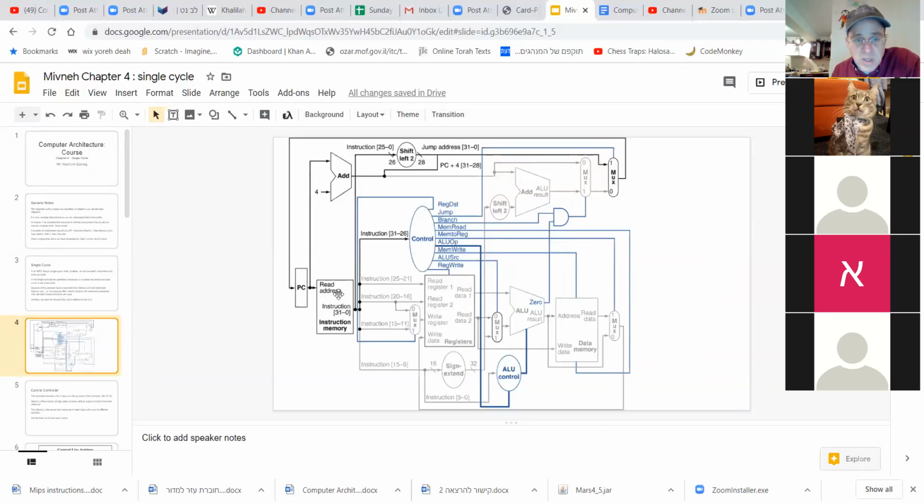It would be, yes. This is instruction memory. It would be between this instruction memory and, I mean, maybe you don't really need a register, actually. I have to think about it. I think maybe in the multi-cycle, it's in the register. I take it back. In the multi-cycle, there might be a register here. There may not be a need for a register.